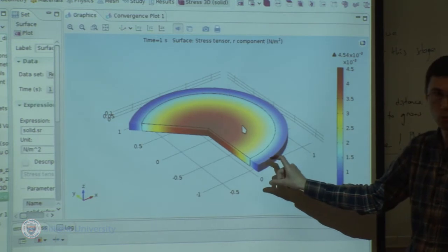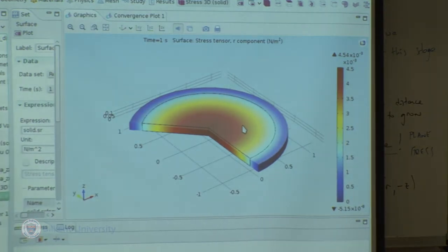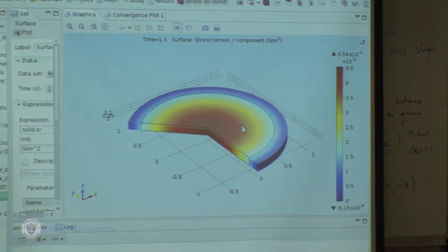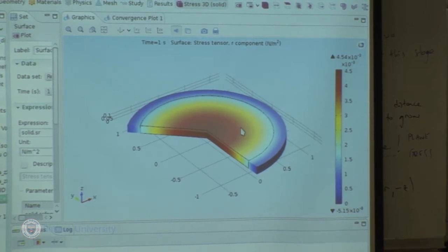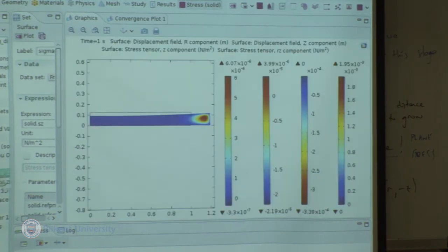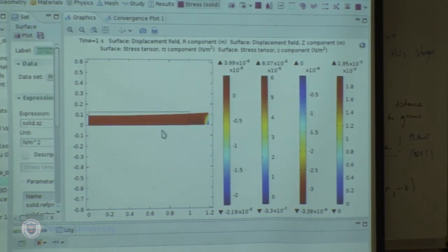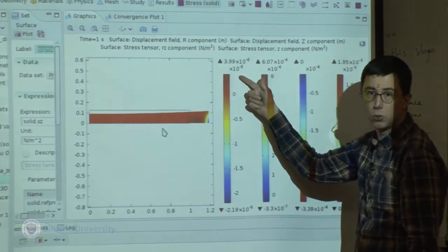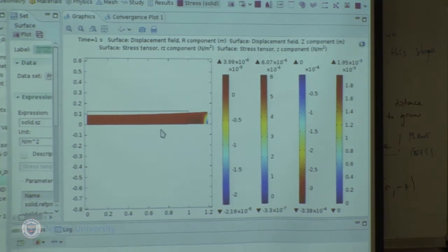The thickness is 0.25 versus a radius of 1. So the thin limit, as I said, should be much, much less, right? It's much less, but in practice, that limit is reached quite rapidly. So the ratio present is just 1/4. OK, so we can also look at sigma ZZ. Sigma ZZ was before not that small. Now, when we look at that, it's also 2 orders of magnitude less than sigma RR. Now, that's fine. When I make it thin, they'll become smaller and smaller. So indeed, I can neglect them.